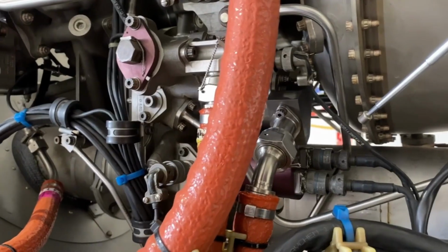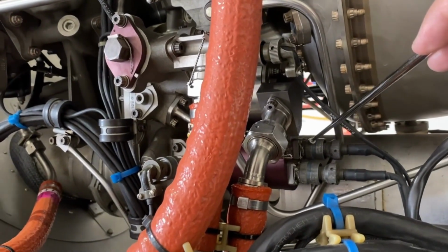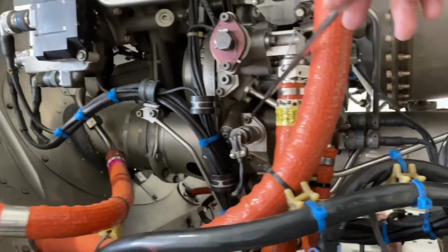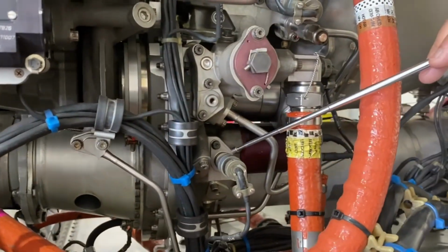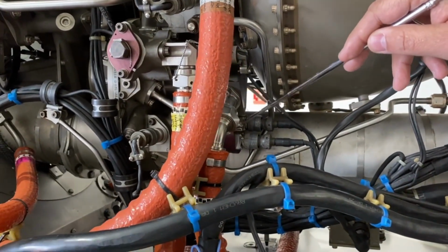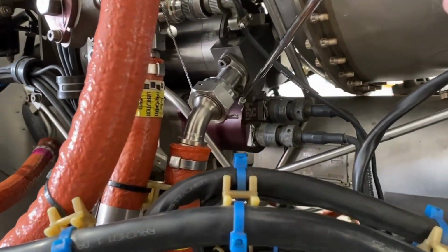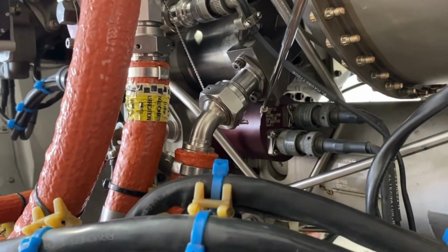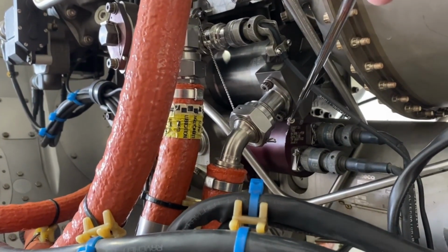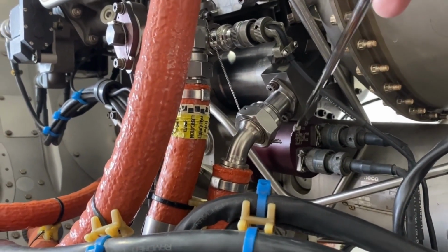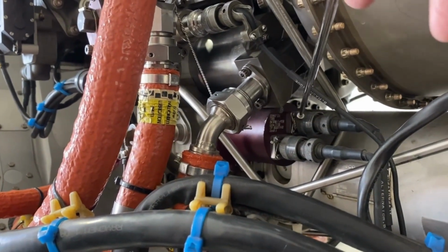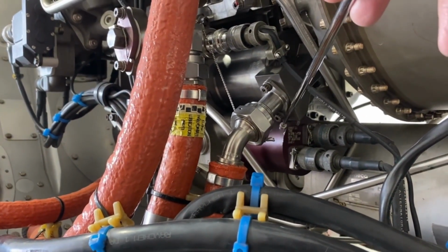The inputs that the FADEC receives are three N1 signals, which it calls N1A, N1B, and here N1C. The difference between N1C and N1A or N1B is that here it is a control alternator. It is the power source for the FADEC. So when you are starting the engine, the FADEC is powered by the aircraft's electrical system. From a certain point in the engine's operation, the one that powers both channels of the FADEC is this control alternator. So it has two functions.